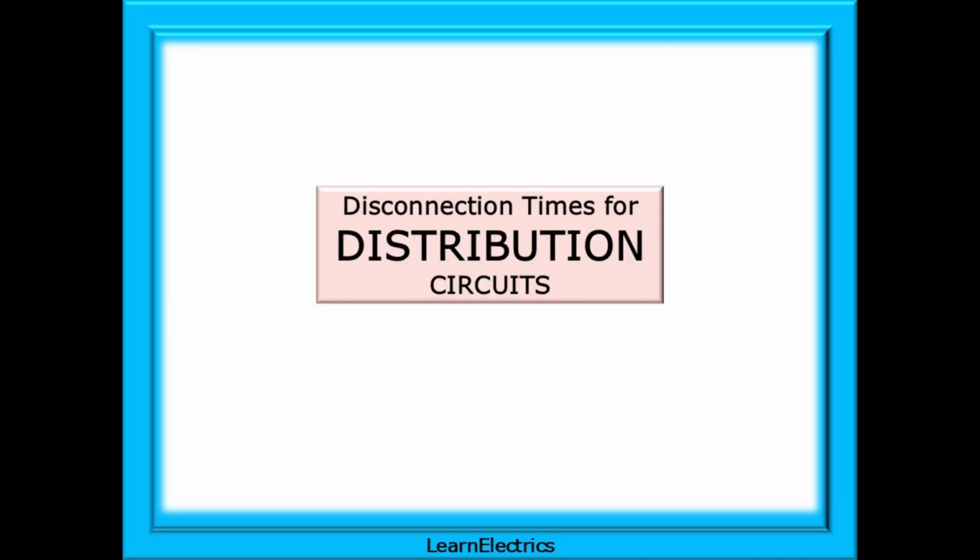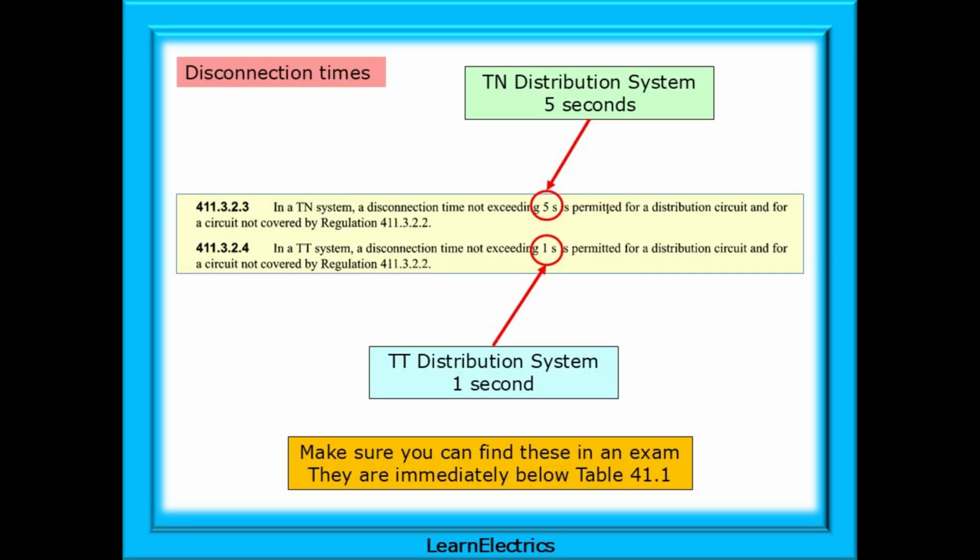That was for final circuits. Will the times be different for distribution circuits? Just below Table 41.1 on page 65 are two important regulations: 411.3.2.3 and 411.3.2.4.